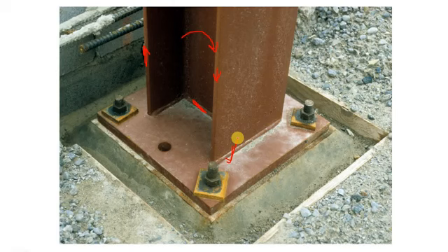Now you can see here that the plate is held in place by these 4 bolts. Also observe the bolt location. They are not within the flange, but they are outside of this flange. So this is similar to the end plate moment connection, isn't it?